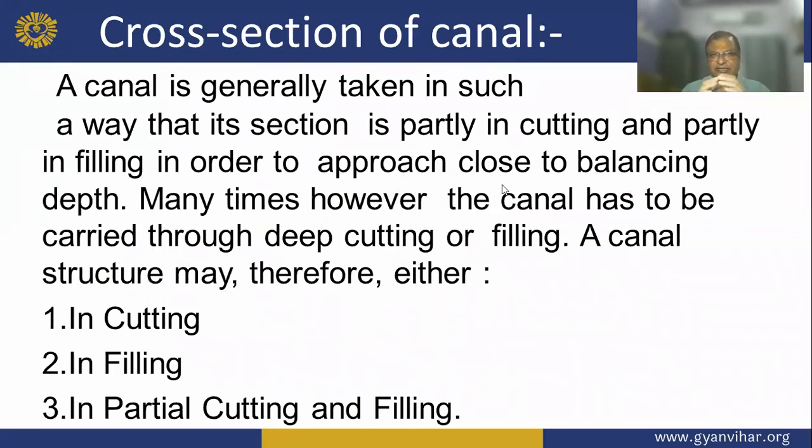A canal is generally taken in such a way that the section is partly in cutting and partly in filling, in order to approach the balancing depth. So many times, however, the canal has to be carried through deep cutting or filling. A canal structure may therefore be in cutting, in filling, or in partial cutting and partial filling.